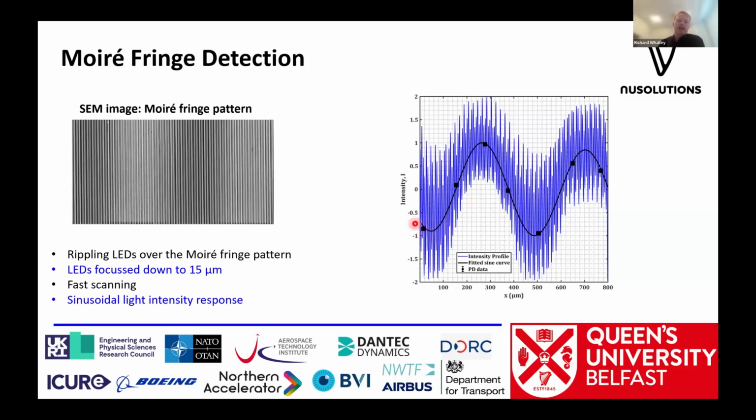And so these black dots here are the response from the LEDs hitting the back of the sensor that's picked up by the photo detector. And so ultimately these lie on this sine curve here. And so ultimately, as the sensor begins to move, those dots begin to move. And then what you're tracking is that sine curve moving back and forwards with time.